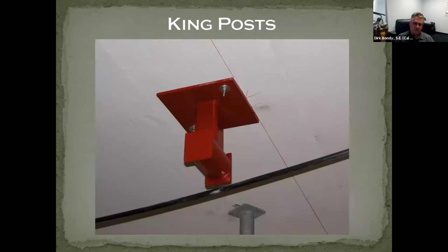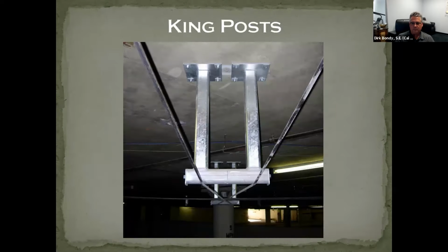King posts, this has got intumescent paint for corrosion and fireproofing, which is important. These are what divert the tendons and actually create the balance point loads. Sometimes they're small like they were in the previous picture. Sometimes we have the depth where we can really significantly create large balance loads, push up on the slab without a tremendous amount of force in the post-tensioning. If you've taken a post-tensioning class, you know that that drape is what you're looking for when you're trying to create an upward balance force.